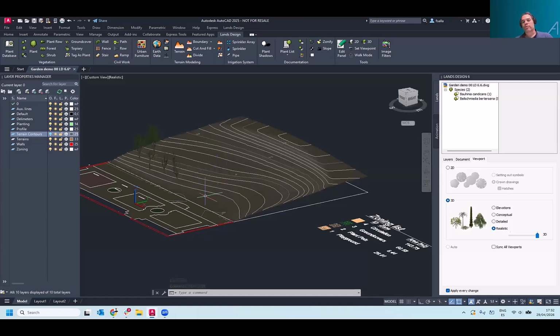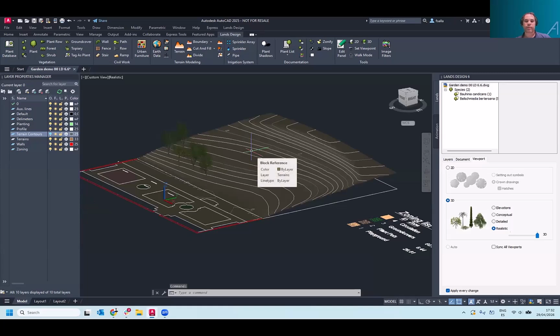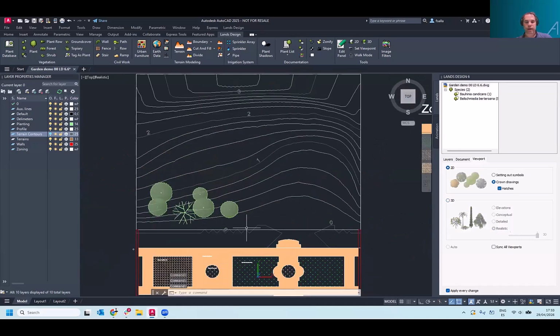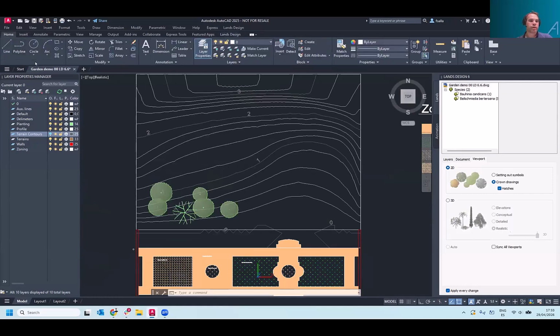What we could do now is to see some of the terrain operation tools. We will add a path on this terrain and see how the moving operations perform. So I'm going to work back in 2D, and I will draw a path curve here that I will use as the terrain path. So I go to Home. I'm going to draw it from a spline, and the terrain path could go something like this. Okay, this is actually now a curve at zero elevation.